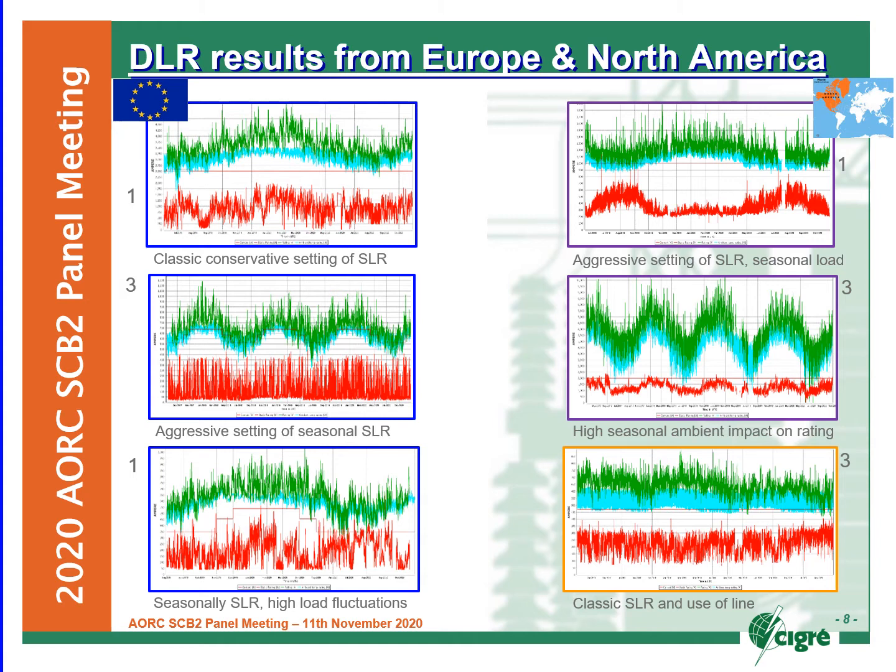The red curves show the line current, blue the ambient adjusted rating, considering cooling from ambient temperature only. And the green shows the dynamic line rating considering cooling also from the wind. The static rating used by the customer is shown as well. In most cases, it's just a flat line, but the bottom 2 of the European systems show that it varies per season.